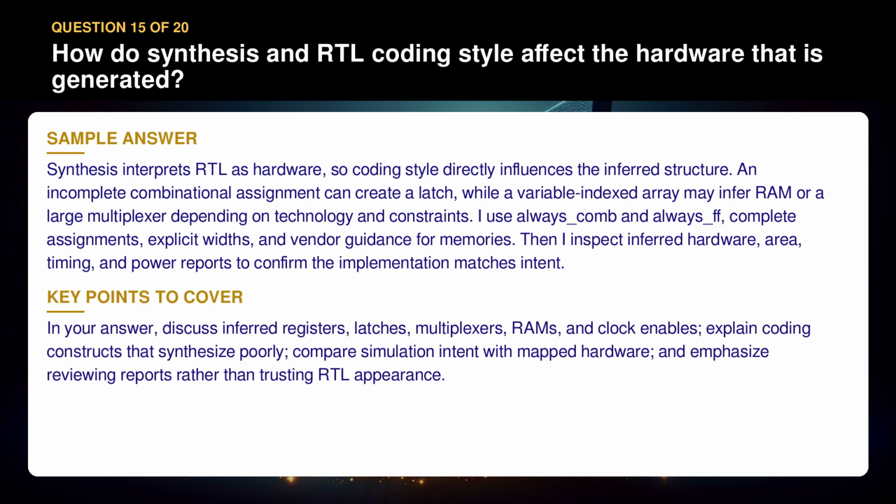In your answer, discuss inferred registers, latches, multiplexers, RAMs, and clock enables. Explain coding constructs that synthesize poorly, compare simulation intent with mapped hardware, and emphasize reviewing reports rather than trusting RTL appearance.